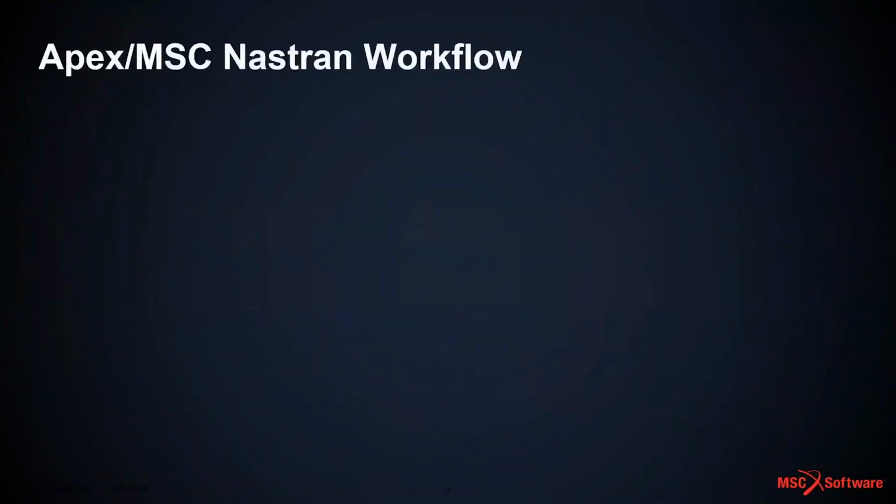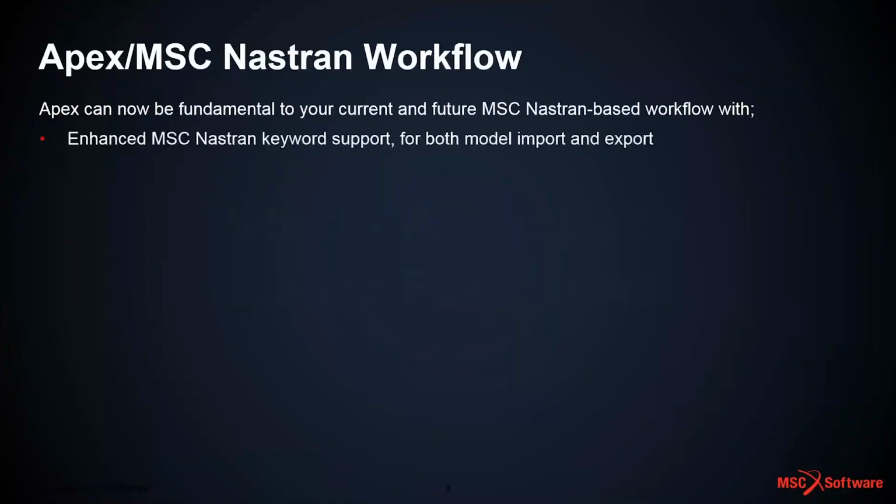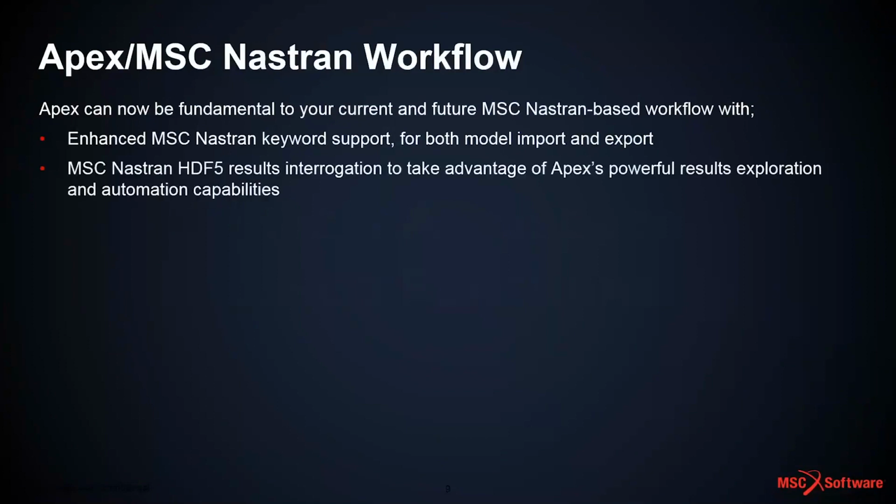So first of all, we'll look at the Apex MSC Nastran workflow. So Apex is, or can be now, fundamental to both your current and your future MSC Nastran-based workflow, with far more enhanced MSC Nastran keyword support, both for model import, so reading bulk data or load case entries into your Apex environment, and also exporting that information back out for external MSC Nastran-based analysis.